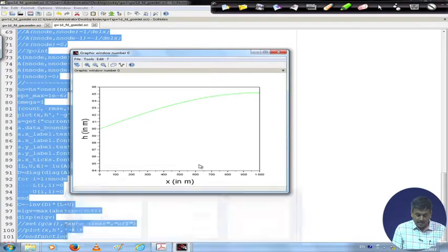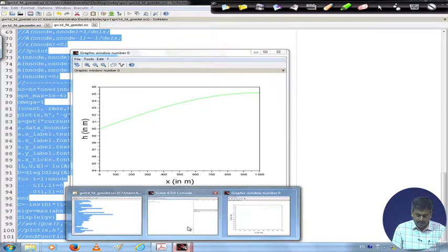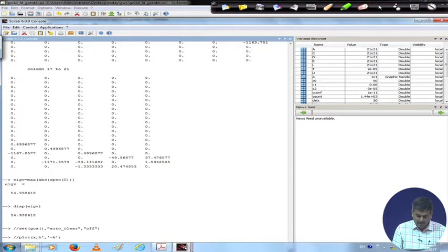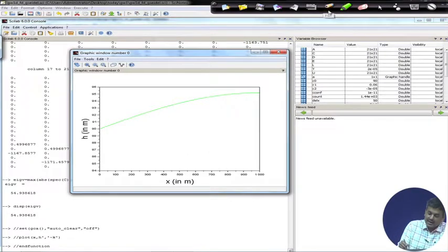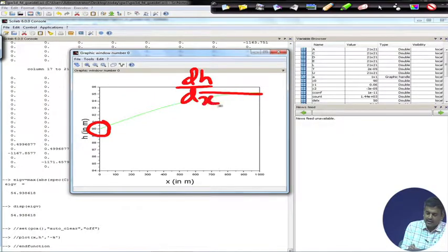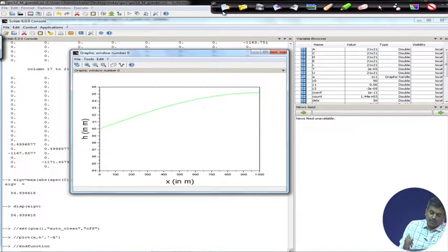So if we run it, we can see that we are getting some solution out of this, and the solution, again this is 90, and again it is matching in terms of the physical nature of the problem. It is interesting that by seeing the boundary condition itself, we can test the nature of the solution, or whether your solution is of the correct type or not. So in this case the things are working, but still the diagonal dominance criterion is not satisfied.